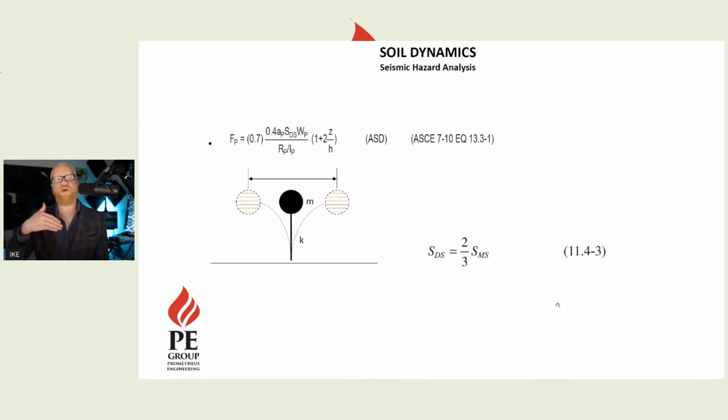So the spectral acceleration is defined like this. It is the response, this acceleration response. It's important that we get this part. A spectral acceleration is the response, and response could be displacement, velocity, or acceleration, a response of your structure due to an input motion. Due to an input ground motion in this case, how will a 1 degree of freedom system with a particular frequency respond?